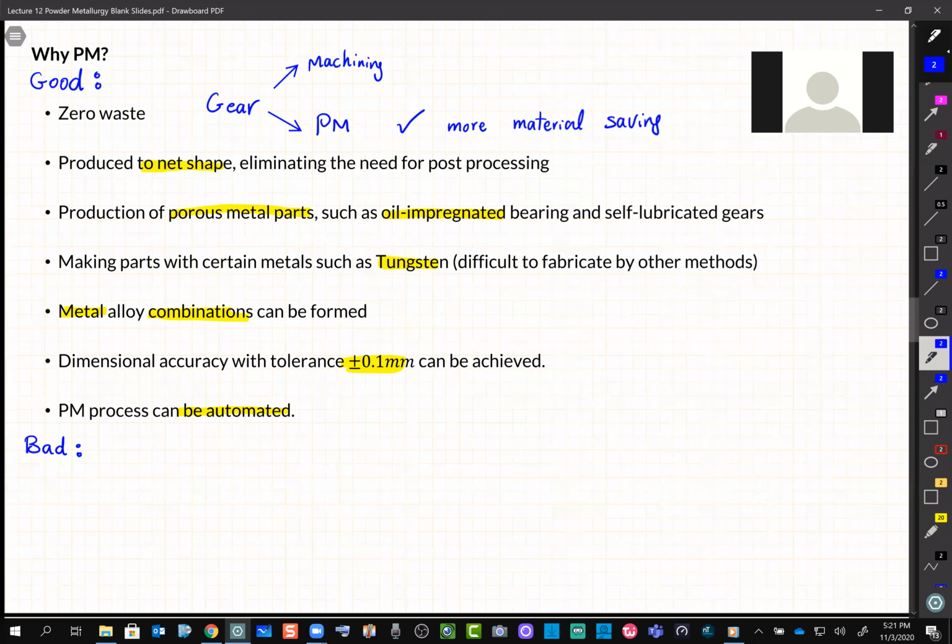It has uneven density and probably the material properties change throughout the material. But Ahmad, we can say because it's powder, it's uniform, right? The density and the property can be uniform everywhere because it's just tiny, tiny particles. Unless we make a bulky part where we cannot sinter the middle core.